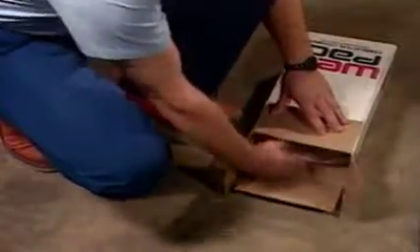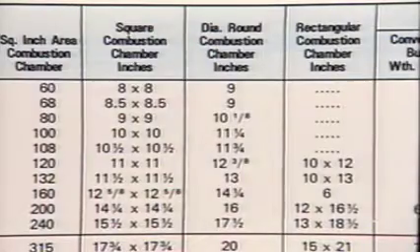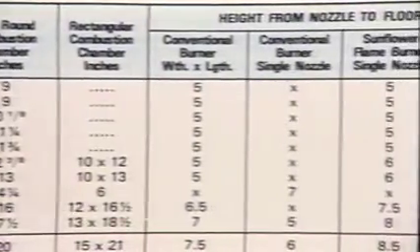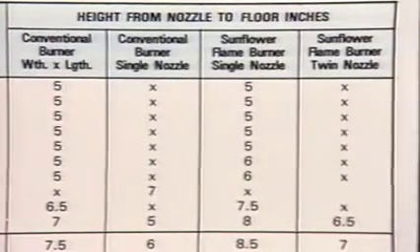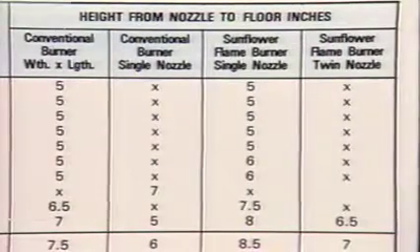Chambers can be quickly repaired using this packaged ceramic lining kit. It comes out of the box wet and flexible, so it's easy to install inside a chamber and mold to fit the chamber shape. When the chamber is fired, the material becomes rigid. Sizing data for square, round, and rectangular chambers is available in a convenient chart. It also gives the ideal wall heights based on the burner firing rate.